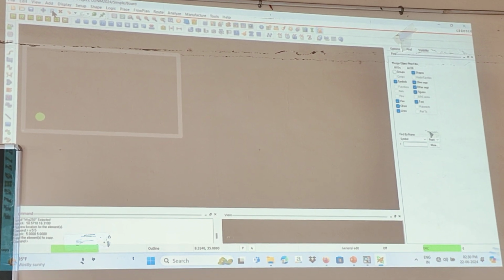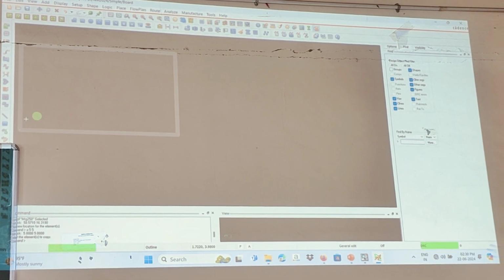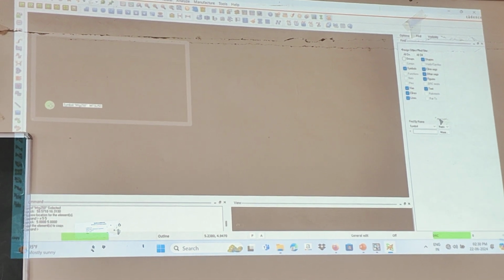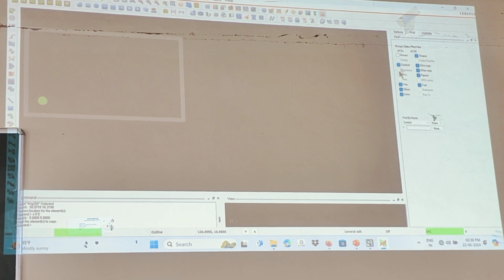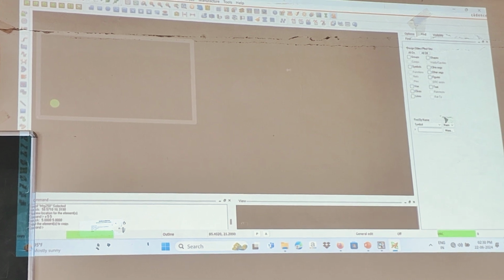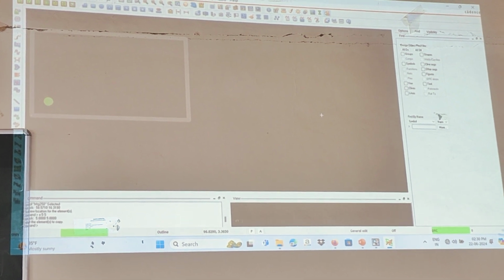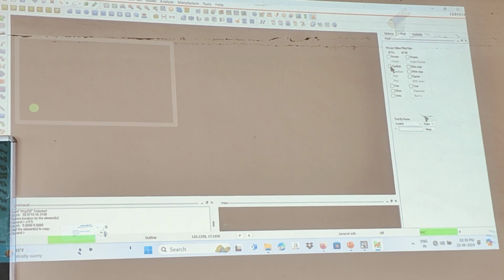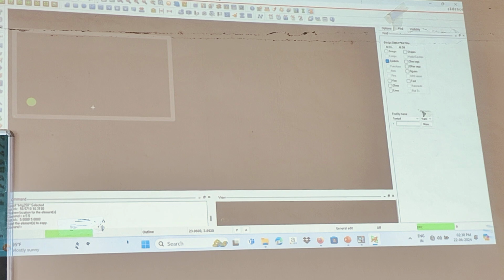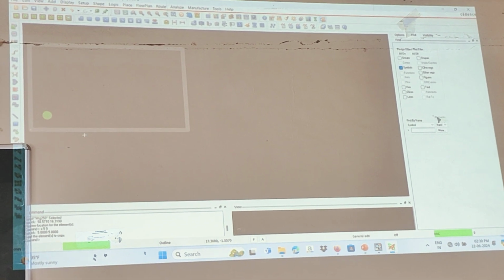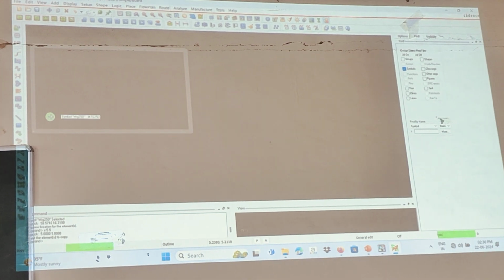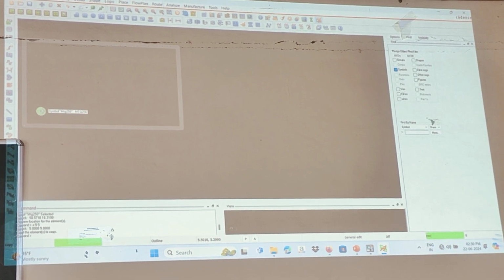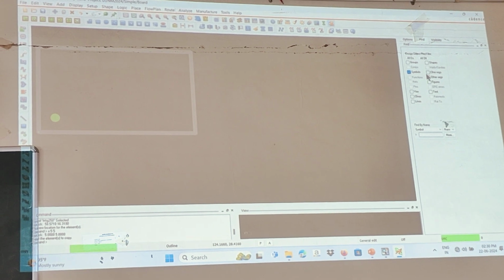So just select copy and click the pin which we want to select. Here also you can see it is being highlighted, the board geometry outline, and the pin also, because here in the find window everything is selected. Just click all off, then we can see there is no highlight. I am just going to move the pin alone, a symbol we can say. I am just selecting the symbol. Now if we move here, the line is not highlighted, but the pin alone is highlighted. For this reason we have to check the boxes whenever we take the tools. We have to go to the right side and verify this region.